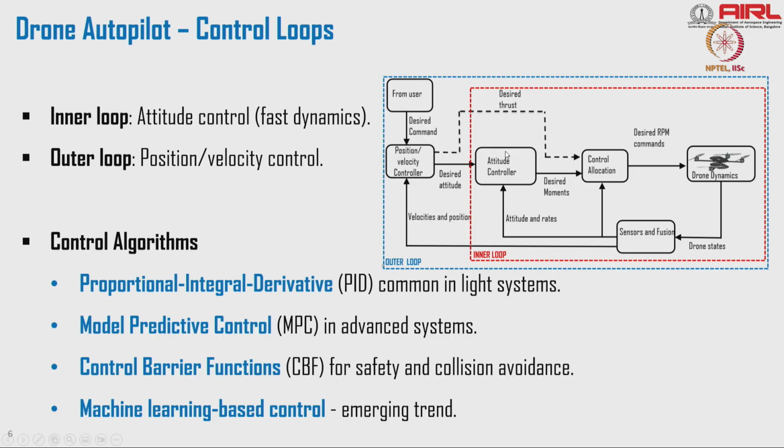My flight controller takes care of it, right? The control system we are developing is going to take care of that. It could be PID control, or pole placement, or a tracking control mechanism, or a model predictive control mechanism. One of those will take care of it, and it will produce the necessary control inputs required. Those control inputs need to be translated into RPM requirements. That will take care in control allocation.